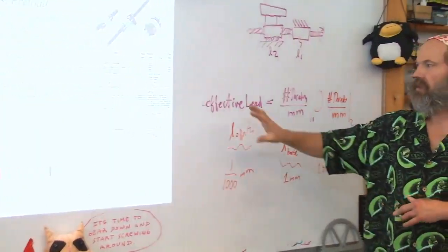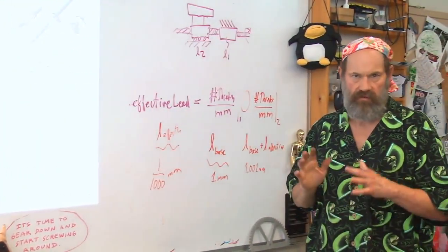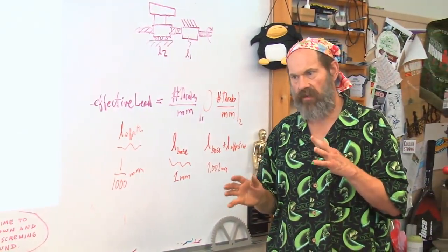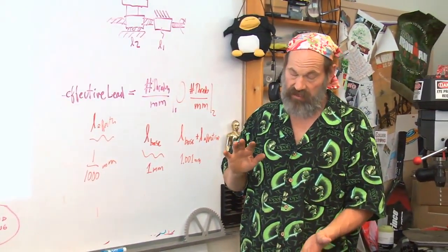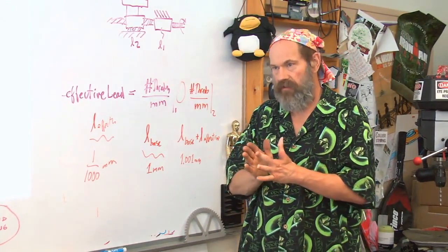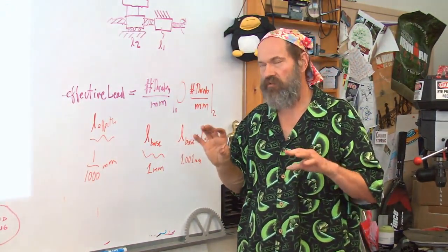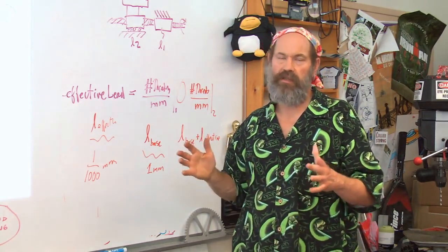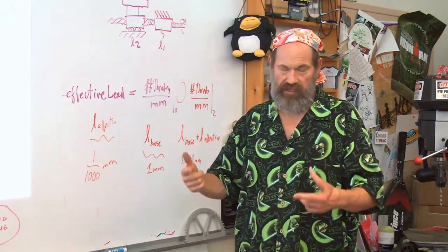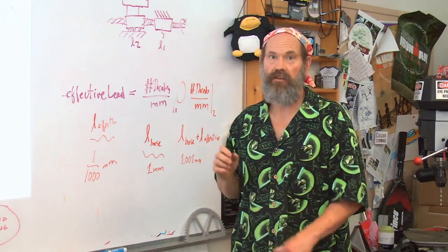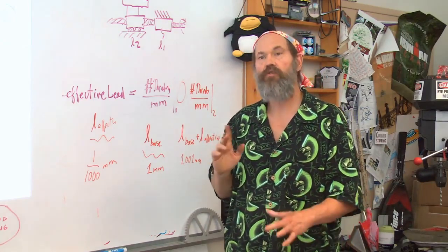So very doable, but you have to be aware of how much backlash you're trying to accommodate and the spring action of the nuts and the shaft to make sure you don't arbitrarily put so much preload on this system that you're lessening the life of it, because you can use up the life of the machine by having too much preload.